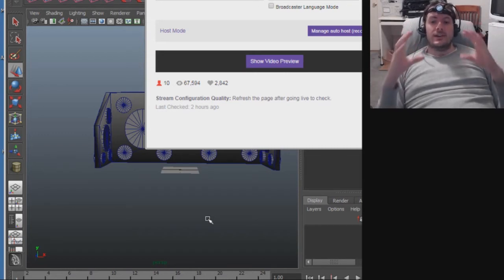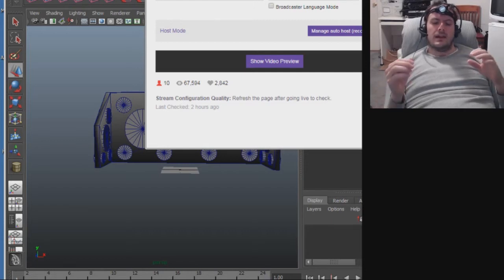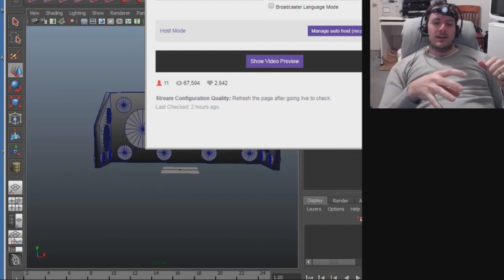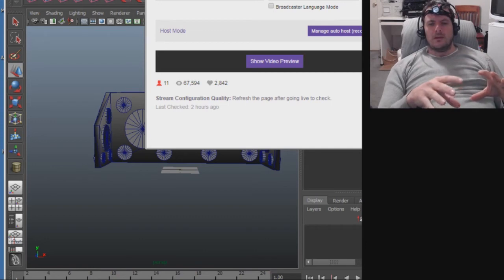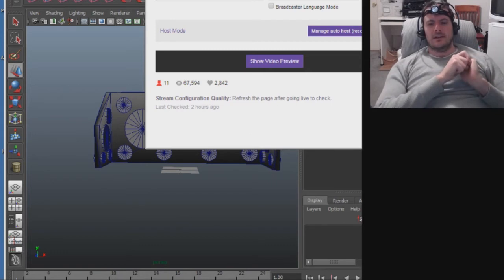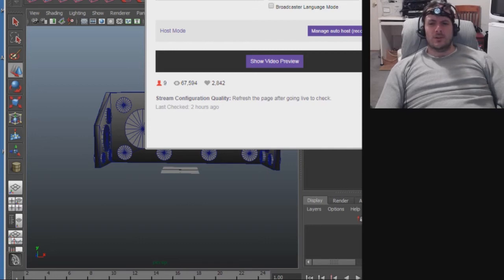I mean, well, first you take your STL from the customer and you bring it into MeshLab and you convert it into an OBJ and export it as an OBJ. You import the OBJ into Maya, you add the holes in Maya, and then you export from Maya as an STL. You import the STL into your slicer software, which then converts the STL into G-code. Then you transfer the G-code to your 3D printer. So that's the workflow, and that was really hard to even say now after having slept 7 hours. It was very difficult to conceptualize all this complicated stuff while I was half asleep last night trying to do this.